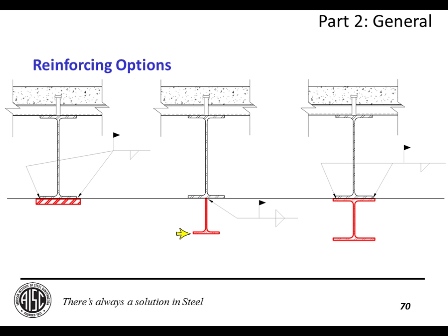So what I recommend doing is adding a W section, like a W8, W10, something like that, where you need a lot of additional reinforcement. And this sort of has the best of both worlds in that you can clamp the member to the bottom flange temporarily. You get a downhand weld if you size the W shape correctly to be wider than the flange of the existing beam. And you also still get your material hanging way out here for your calculations. If you're being judged by every pound, obviously this does add more material to the job. But if you're in a design build situation or you're actually working with the erector, then this would definitely be an option to throw out there.